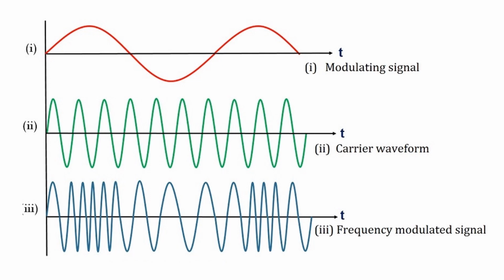At the instant where the phases of the unmodulated, locally generated carrier and the FM signal match, we get zero amplitude. As the phase difference increases due to the deviation in the FM signal, we get non-zero amplitude. Generally, for Fc plus delta F, we get positive peak amplitude, and for Fc minus delta F, we get negative peak amplitude in the envelope.